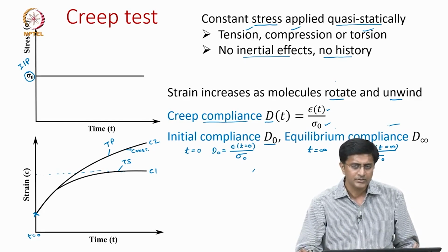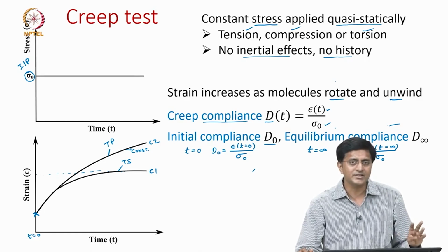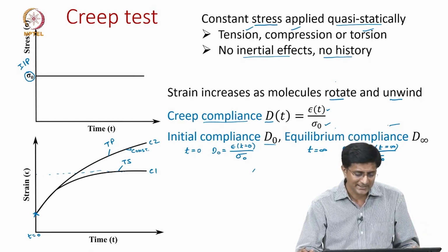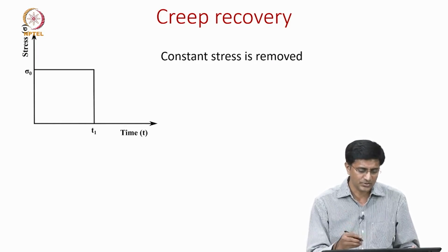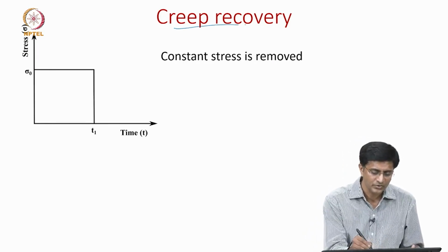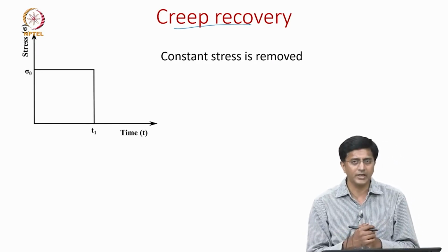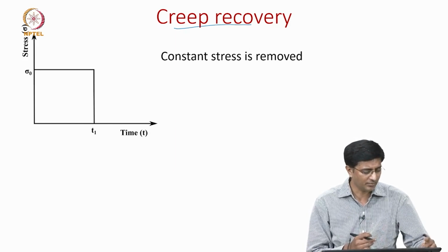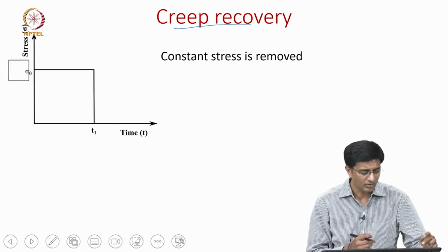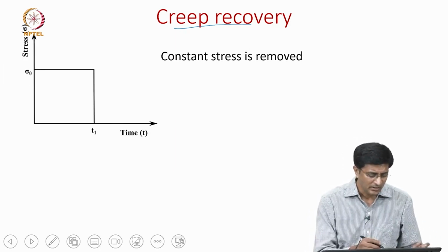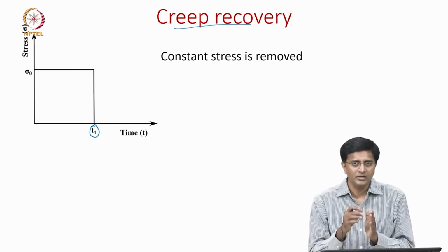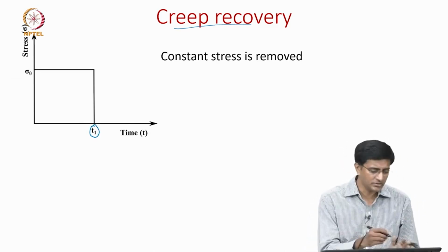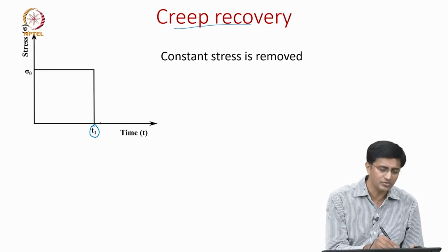Okay. So, now that we have looked into the relaxation test and the creep test, there is another test which commonly is used, which is called the creep recovery. So, it is very close to the creep test, because even like in creep test you apply a constant load, but the only difference is, let us say around time t equal to t1, after a while you just remove the load. So, means the load goes back to 0.